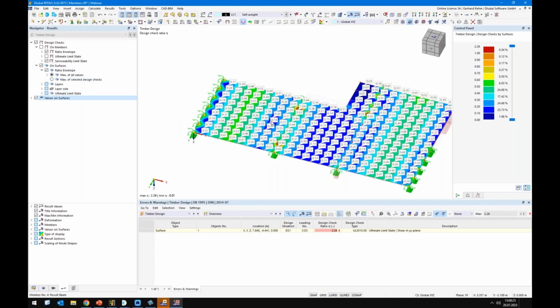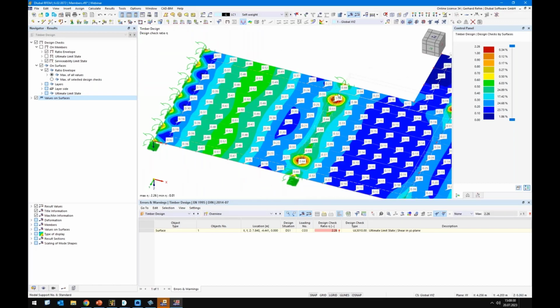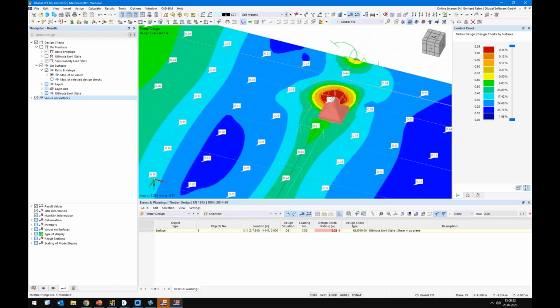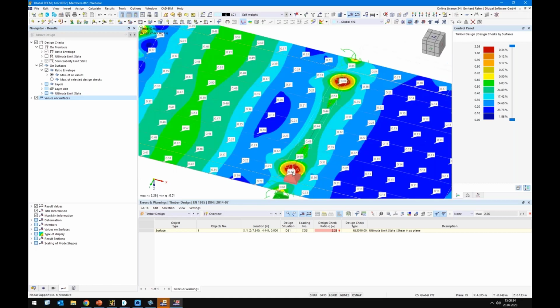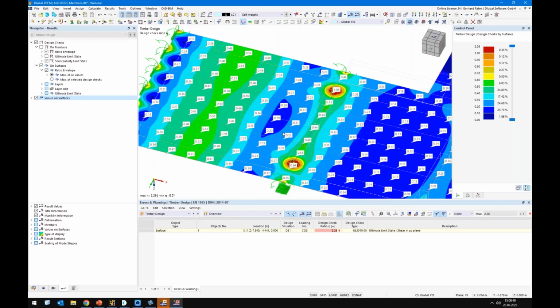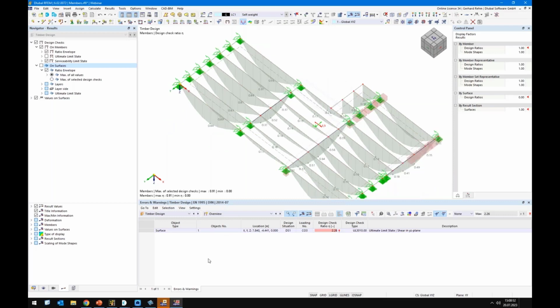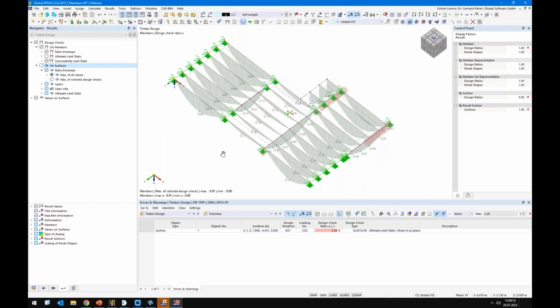Okay. So, and here the ratio is, we have here a problem. I'm sure this is because of the rolling shear and this singularity. This needs to be analyzed a bit more detailed. We have no time for that today, but in general, it looks okay with 50% ratio for ULS, and for SLS, we have around 85–90%, which is also okay. Okay, that's actually about this design of the floor.